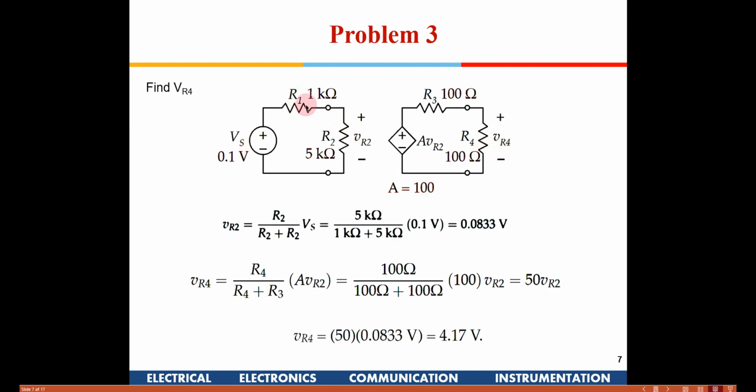Because the source will have a series resistance, so some amount of voltage gets lost here. Also, the amplifier will have an output resistance. So these are not ideal sources. Had these been ideal sources, you would get the total gain of 100. But because of these practical limitations, there is a series resistance along with the source, and the amplifier also will not have an ideal output voltage.